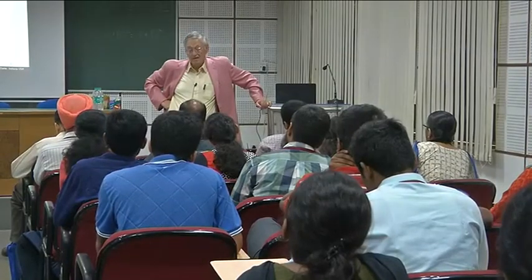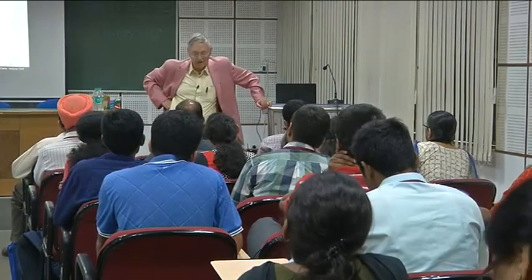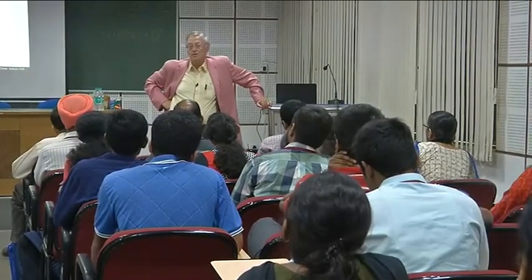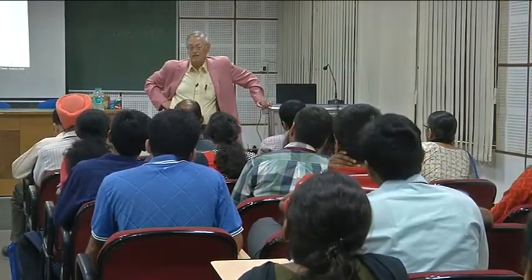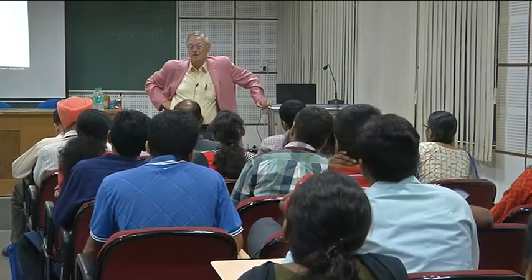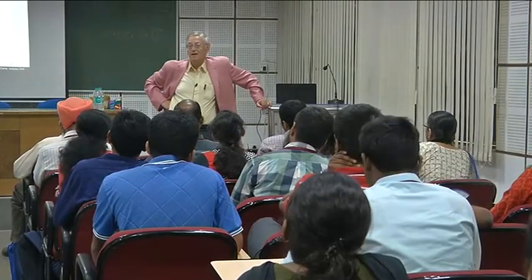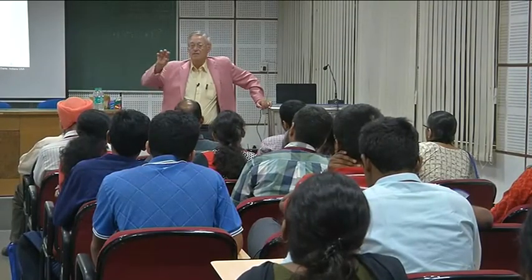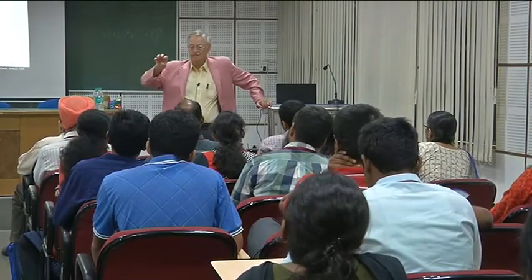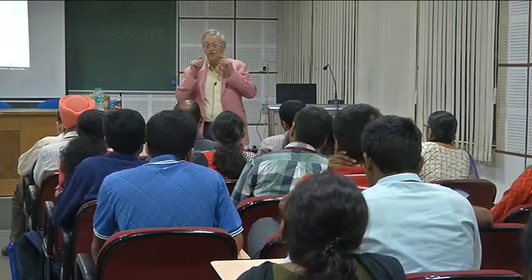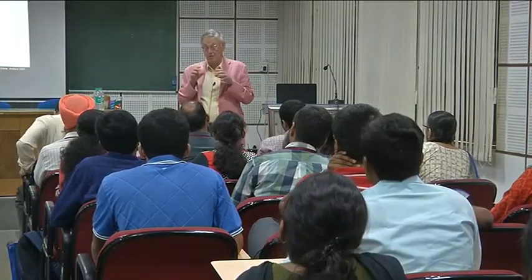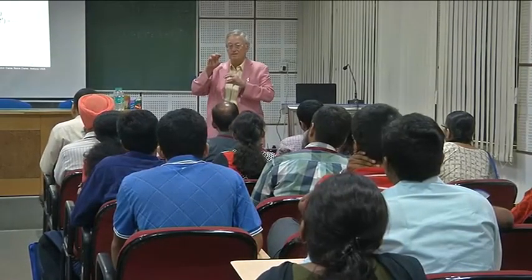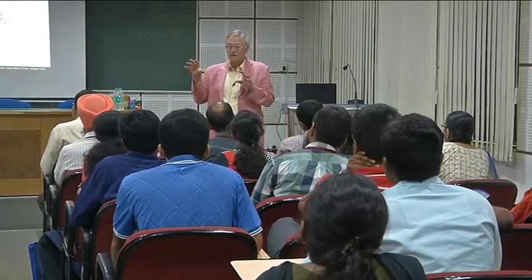Now, I will say that the analysis that you wind up with there would assume that you're using maximum likelihood decoding on that turbo code. That's not the way they're decoded. They're decoded iteratively with individual MAP decoders. The BCJR algorithm, which we'll talk about tomorrow morning also. But it's not one overall BCJR decoder.